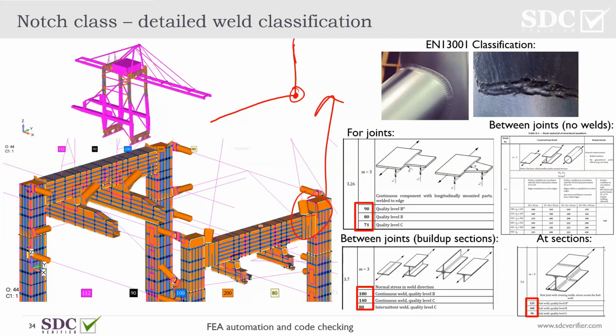So basically, it takes into account the stress concentrations, which are very often mentioned with factors in multiple standards. When you do this, it's fairly enough, and based on experience, it shows very representative results when you do shell modeling, which takes into account with the modeling approach the stress concentration, and then you take into account appropriate classifications, so notch classes. Even if it can be that I have a slightly, maybe relatively more, conservative outcome compared to the real situation, that's still a tension point.